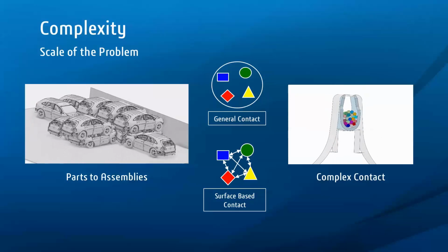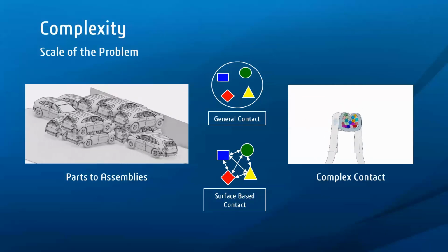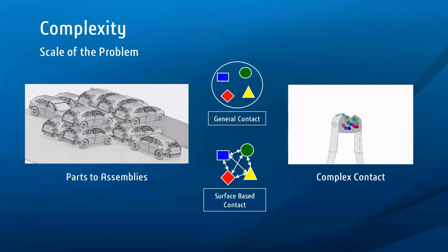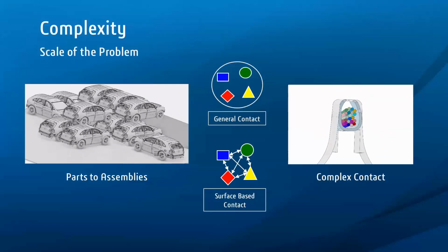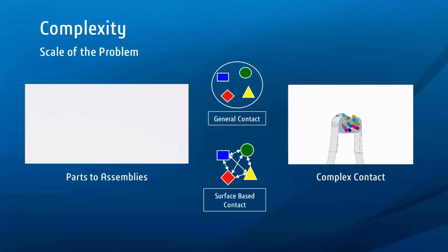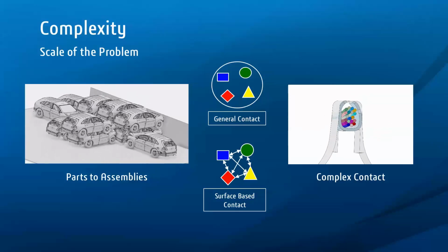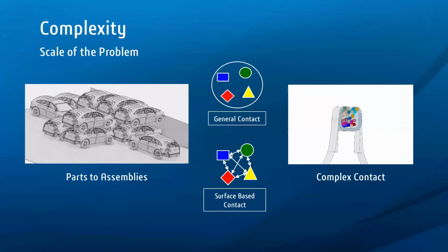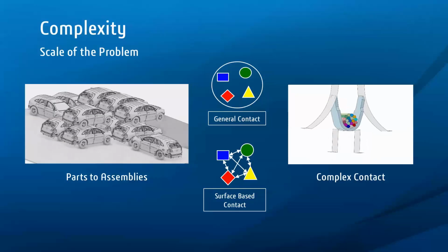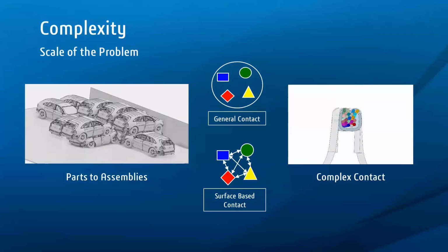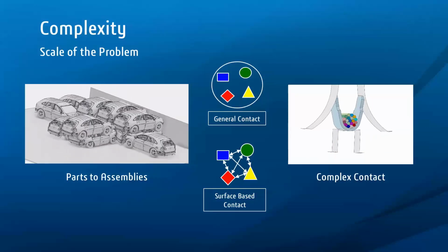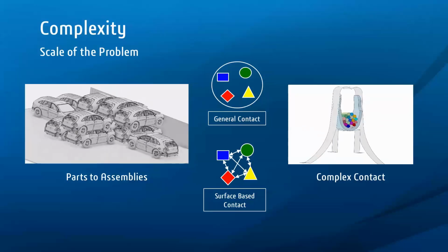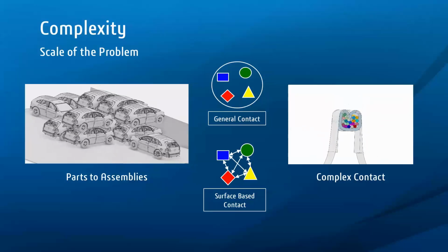Here you have the choice to define contact relationships using either a top-down general contact approach, where everything may contact anything at any time, or define contact based on a bottom-up approach specifying contact surface by surface. Both methods are robust and accurate and can be used together to quickly define these component-to-component or self-contacting relationships. As stated before, we can define multiple contact properties that can be reused to reduce configuration time and increase productivity.